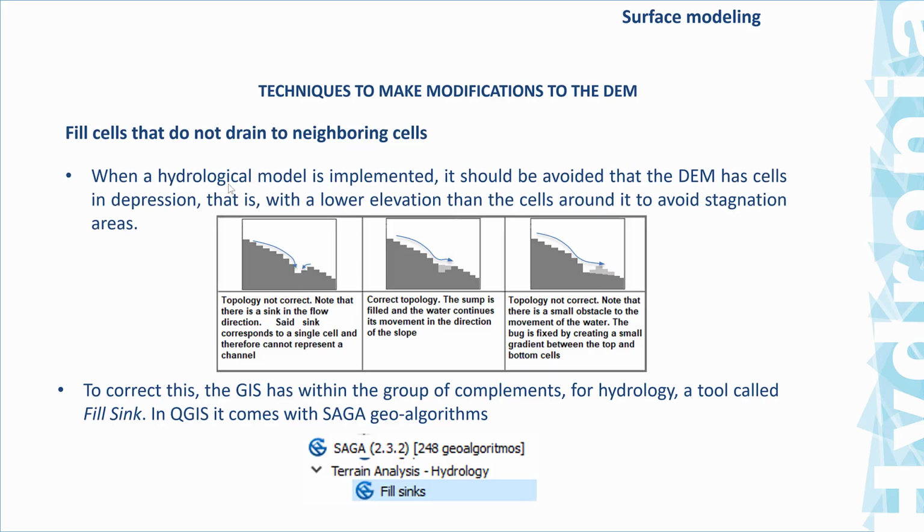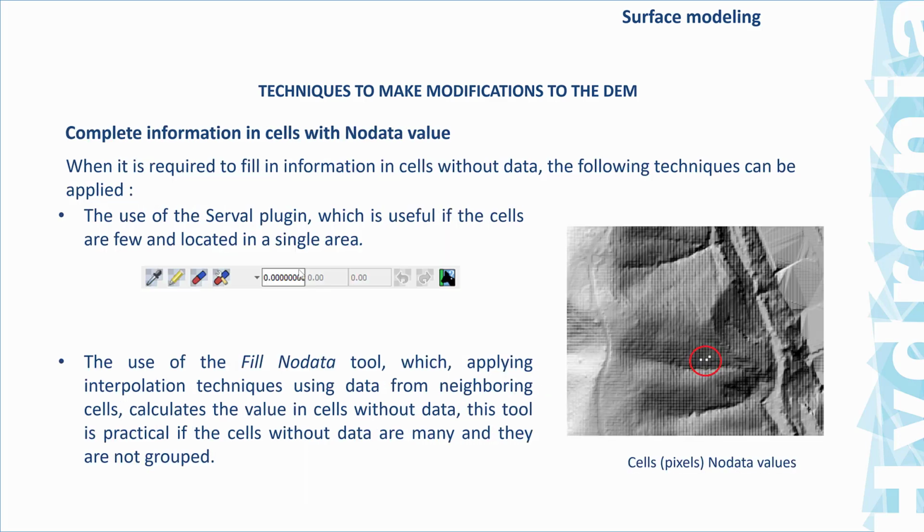There are also situations when doing hydrologic modeling where the interpolation made contains holes that are not representative of the actual terrain, and these are artifacts of the DEM and need to be filled. That's the case of some situations where you get an artificial depression and then you want to fill it out in order to avoid getting water in areas that are not realistic.